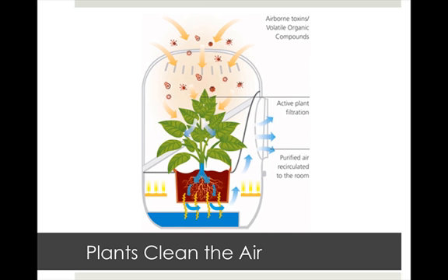So plants also will clean the air in addition to wind protection, shade, noise reduction, and air temperature maintenance. So when you're choosing plants for your project's landscape, or if this is something you do as a designer, consider their shape, their density, the density of their leaves, how large they are when they mature, how long they will take to grow, and how they're going to affect all of these features that we just discussed. Lower maintenance and native plant species tend to have the most chance to survive of all.